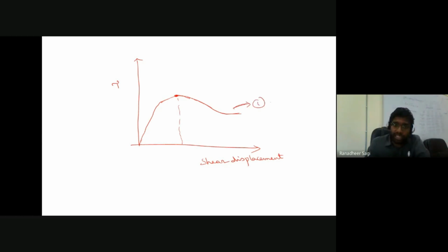In some kinds of soils, you could see the pattern of the curve something like this. Now, what is it indicating? The shear stress that is getting developed along that failure surface is continuously increasing. At some amount of horizontal displacement getting developed in the soil, we could see that the shear stress getting developed along that failure surface was more or less remaining constant. Okay, so even this condition refers to the failure in your soil sample.